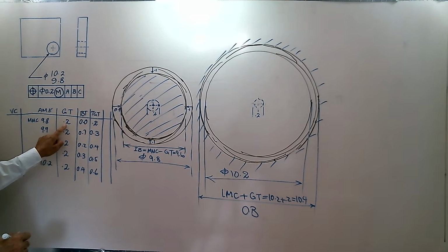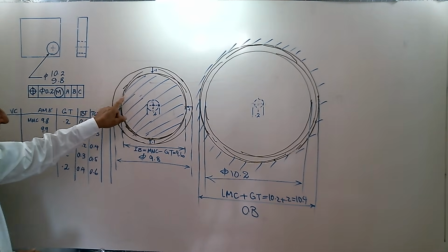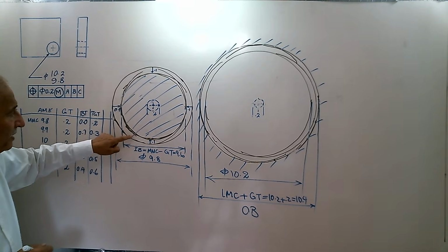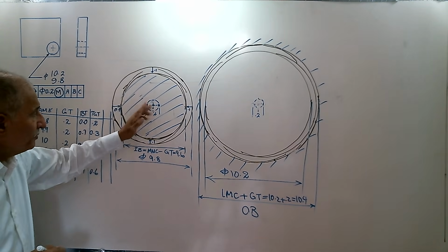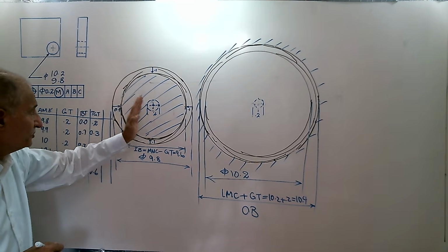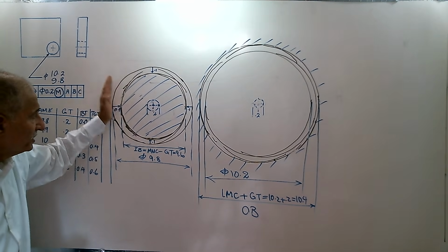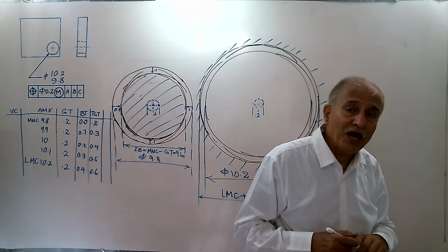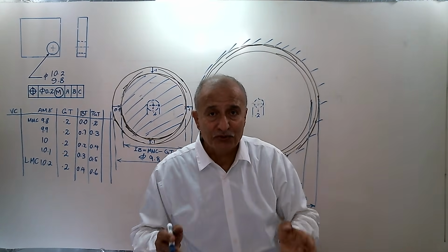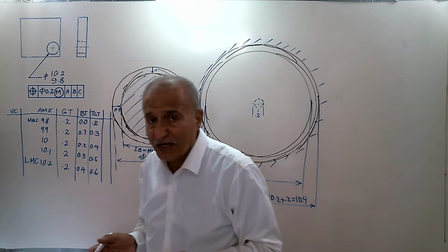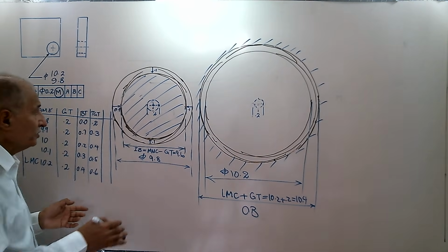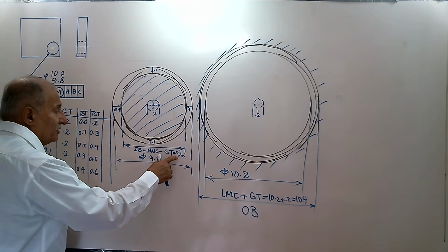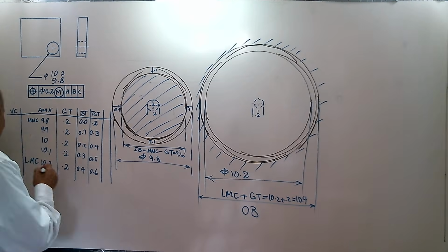9.8 with 0.2 is this, virtual conditions again. Then the hole can be 0.1 left and right shifted, or up and down, or in any other direction. The smallest inscribed circle that you consider that encloses the feature is less than 9.8. How much? 0.1 from both sides, which is 0.2. And again, the size is 9.6. This is what?